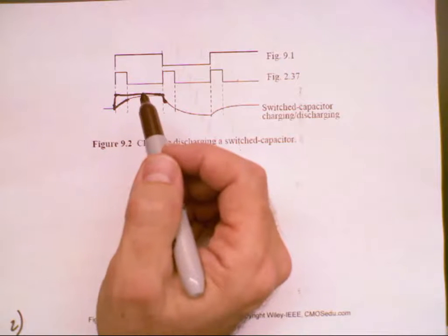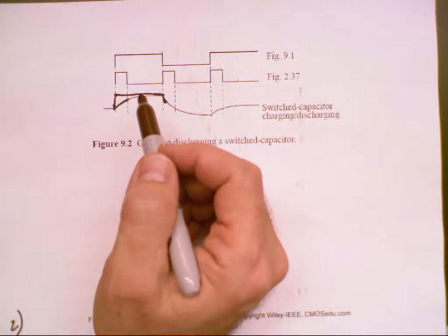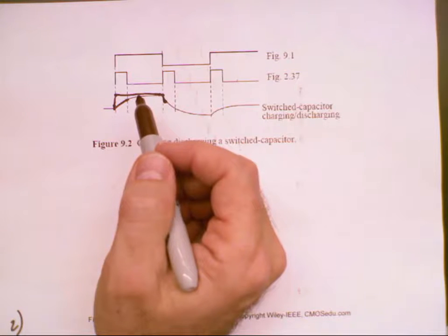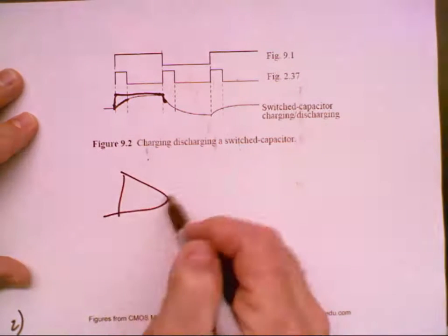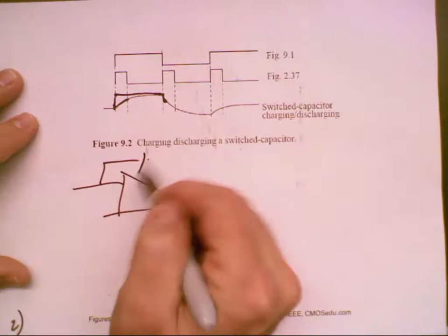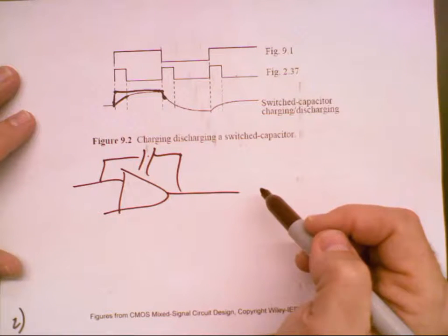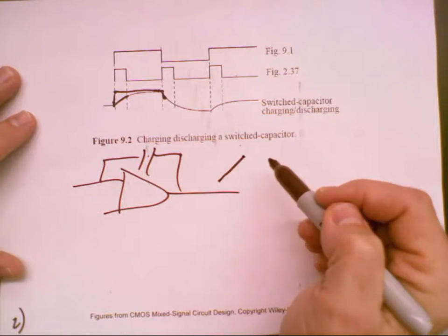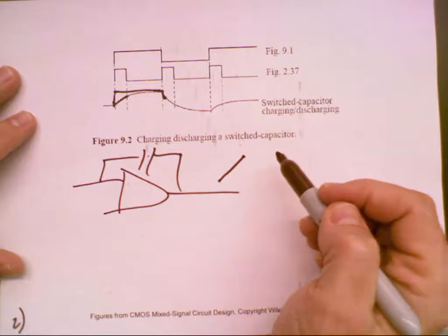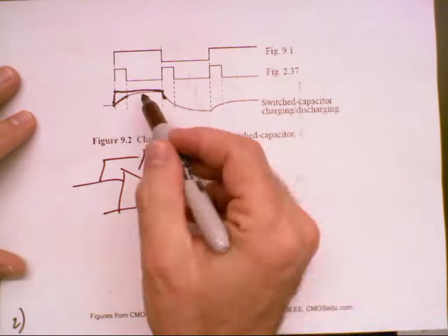What is slew rate? If your op amp is slewing, what's the problem? If I have an op amp and I've got my output here and I'm seeing slewing, show me what you're going to see. Yeah, it's going to be a straight line where it can't keep up. It's not going to be a charging and discharging like I see there.